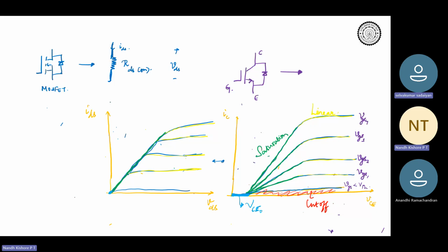It is PNP. Correct. So it's basically a minority carrier device, and that is why it will have this small kind of a depletion region which needs to be overcome. You are right. Therefore, deducing from this, for IGBT conduction there are two barriers to be overcome. Not only the ohmic part, there is also this VCE naught part.